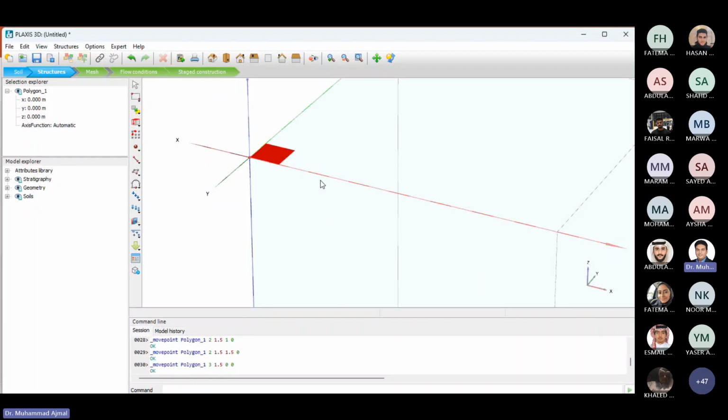Now, as we know that our slab system is resting on the soil at ground level, so I will not model it as a plate. What I will do is directly apply load on this surface. If you have a plate which you want to model in your software, you want to give the properties of the concrete, then you need to model it as a plate.